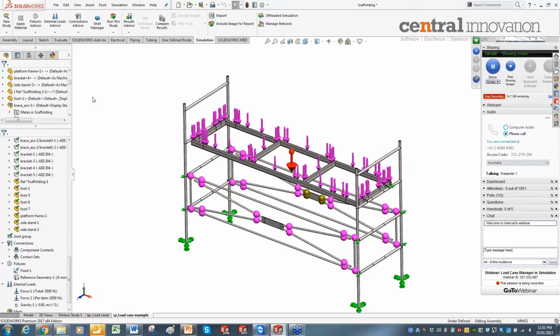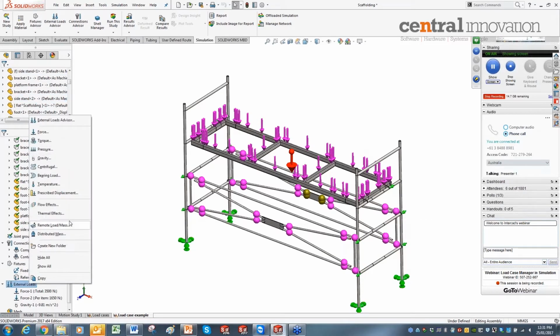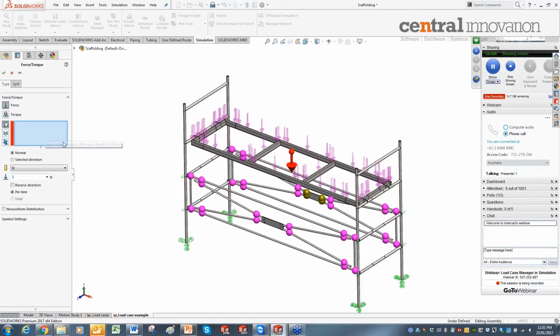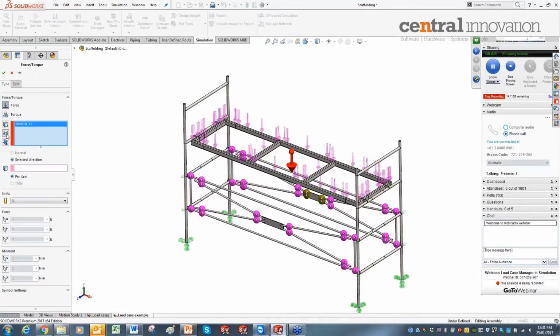And one more thing, like I mentioned, I have done few trials and these beams are not constrained properly. So to make it constrained, I'm going to use some external load. You can also use fixture, it's up to you. There are lots of ways you can constrain it. I'm going to show you how to define fixtures on the joints of the beam. So you can see here, there is an option to select joint. I'm selecting the joint.